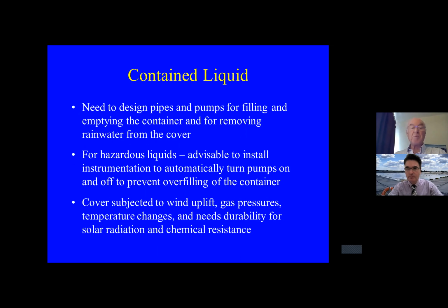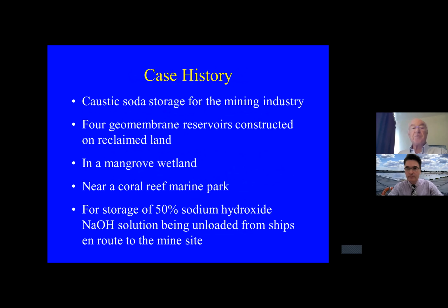I won't spend much time on this because we haven't got much time, but there's all sorts of things you need to design for the liquid, the pipes and the pumps. For hazardous liquids, it's advisable to install instrumentation to automatically turn the pumps on and off to prevent overfilling of the container. And the cover is subjected to wind uplift, gas pressures, temperature changes, and needs durability for solar radiation and chemical resistance. So moving on to the case history.